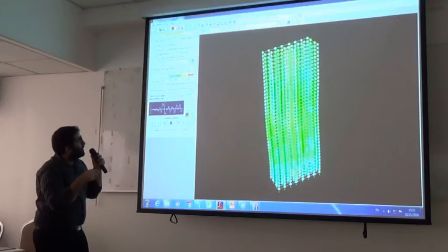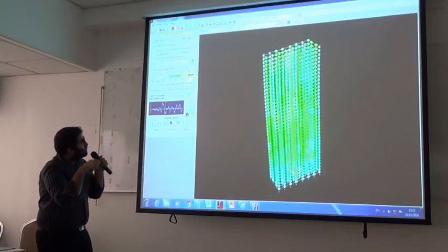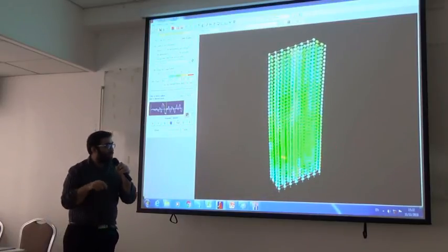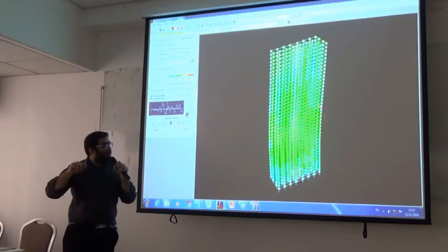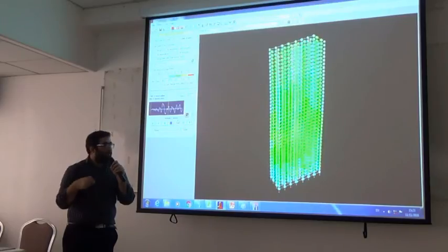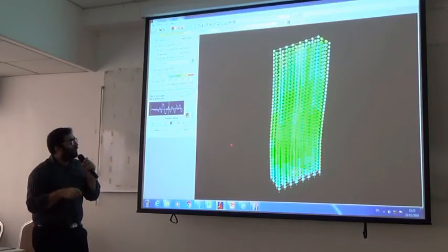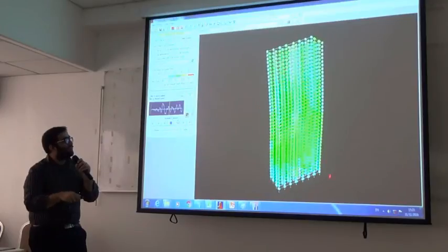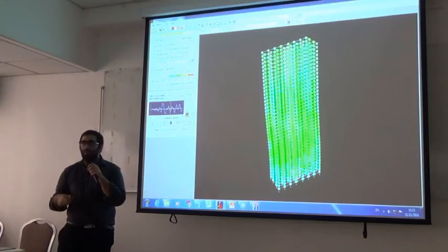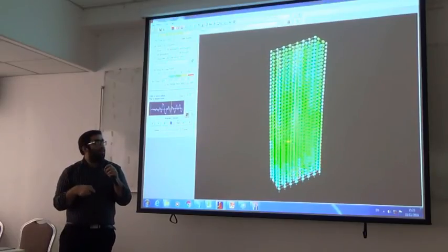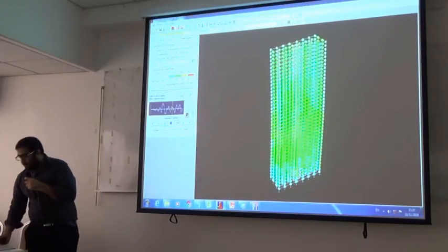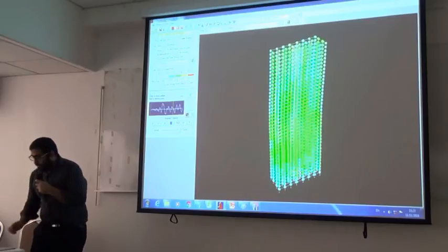And currently we are checking the DC ratios of rotation, right? So the rotation over here is exceeding 0.2 times the deformation capacity that I gave them, but not exceeding fully. If it is fully exceeding, the ratio will be higher than 1, and you will see some red colors forming somewhere. But right now we are not seeing any red color forming anywhere. So basically, the rotation is there. The girders have yielded, but they have not yielded significantly enough.